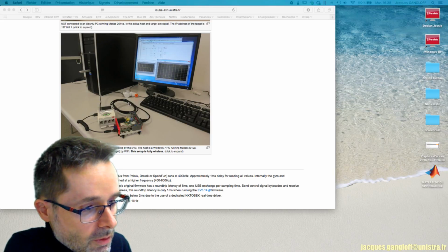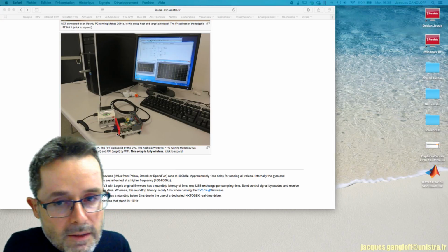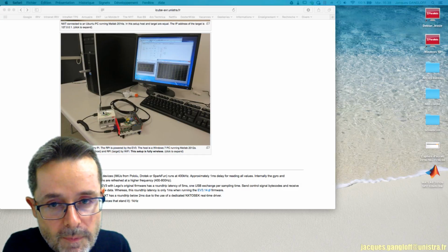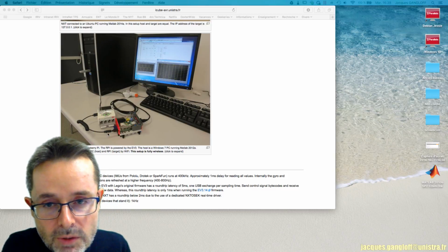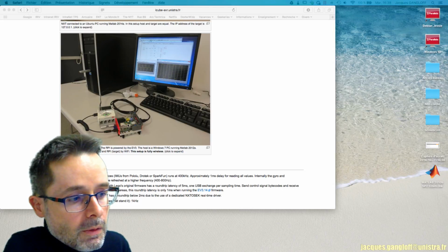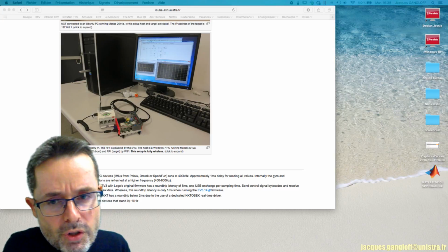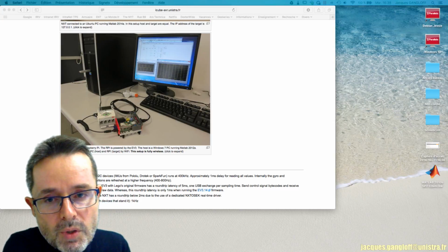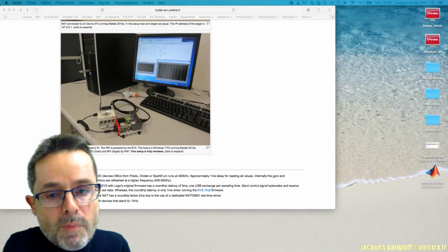There is a USB connection between the Raspberry Pi and the EV3, and the EV3 is powering the Raspberry Pi thanks to the secondary USB port. It provides enough power for a Type 1 Raspberry Pi. We measured that this port is able to provide more than 800 milliamperes.